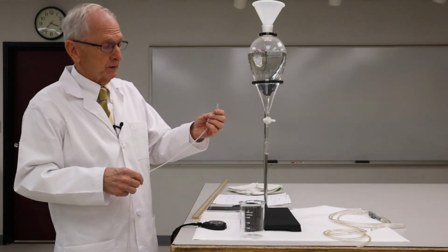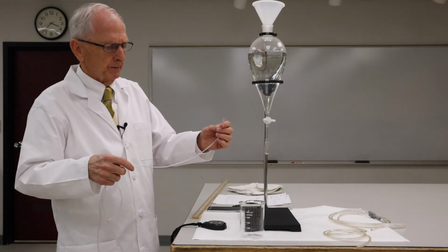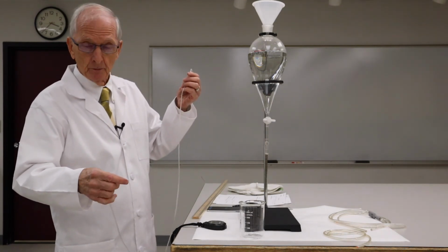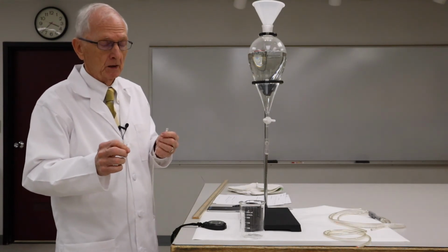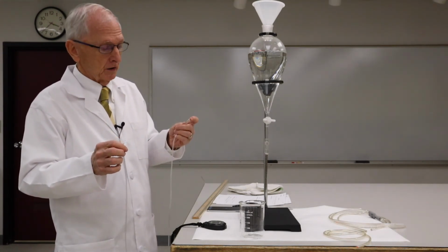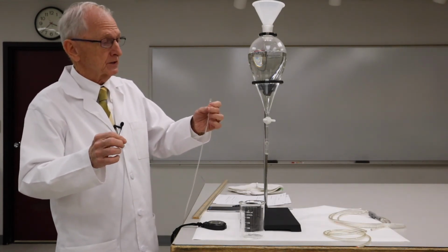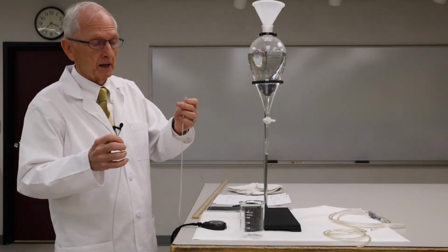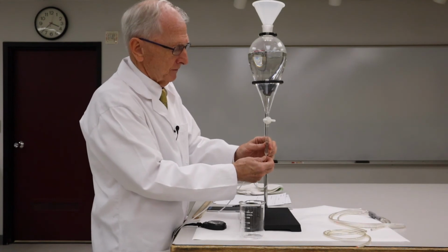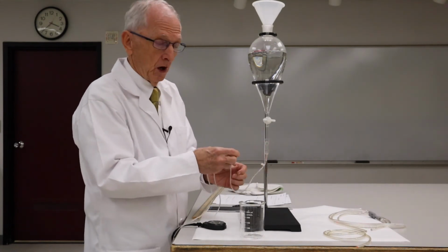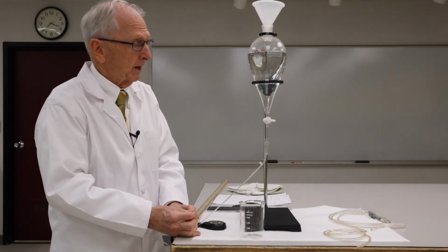Now let's make a measurement of the fluid resistance, similar to what we did before. But I can anticipate something. Since this is longer than the previous tubes, but especially since its inside diameter is much smaller, it's going to take a lot longer to make this measurement, because the fluid resistance of this tube is going to be a lot higher than the previous tubes. So, to accommodate for that so that we don't have to spend a long time making this measurement, I'm going to increase the pressure.